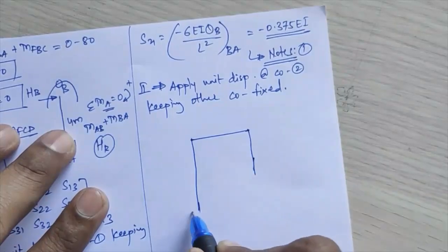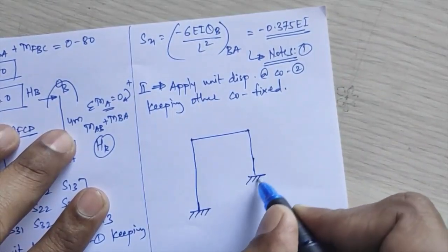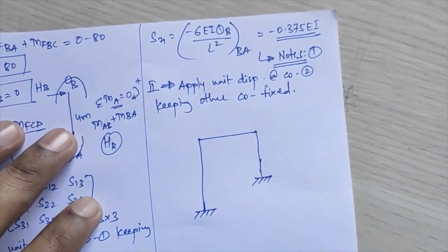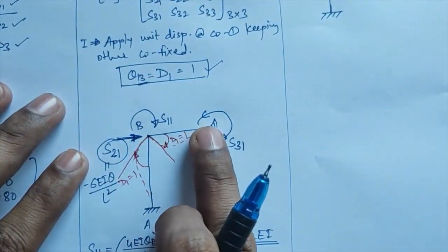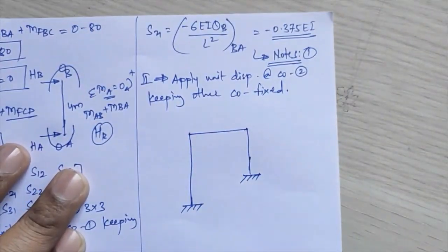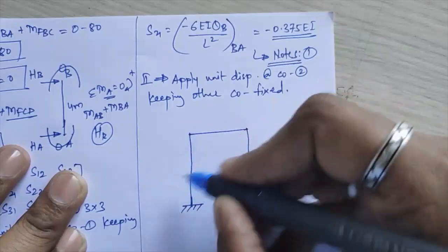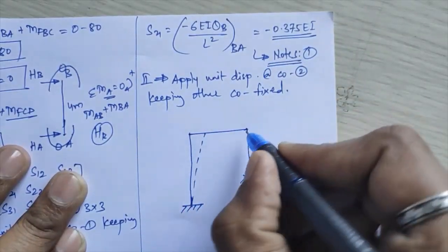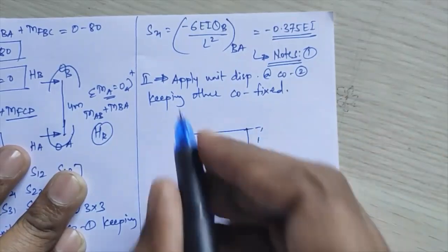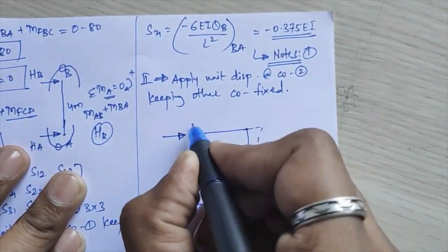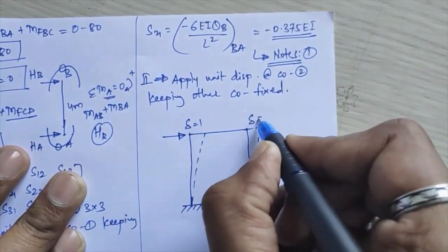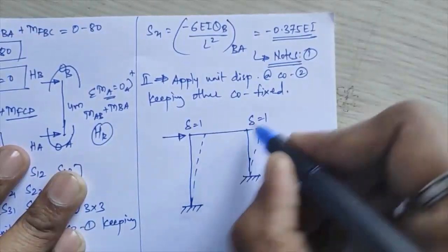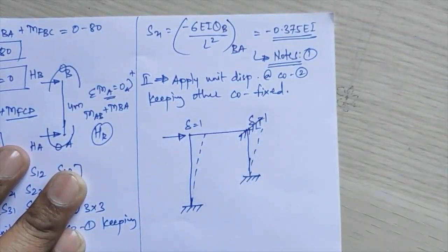Now here your stiffness coefficient will be in terms of delta. Whatever swaying coefficient you will see, the displacement pattern we were taking for theta was for your slopes over there. Now here those displacement patterns will be in terms of delta. So here what you have to do is apply this swaying of this frame due to this lateral load for delta equal to 1 there. Okay, and you have to fix the remaining joints here, right?